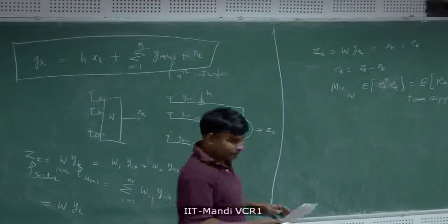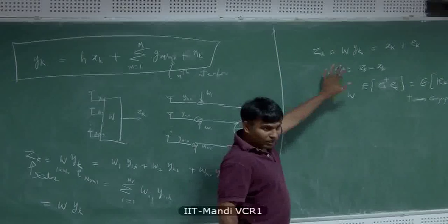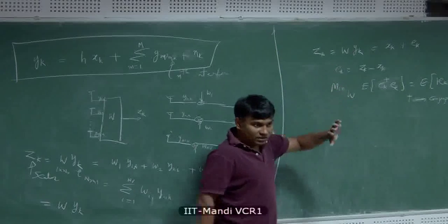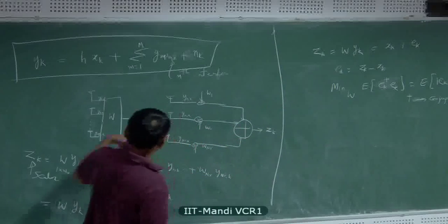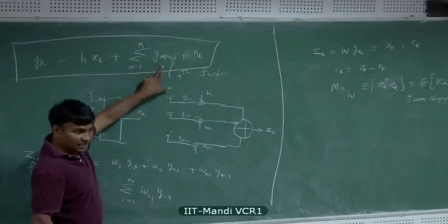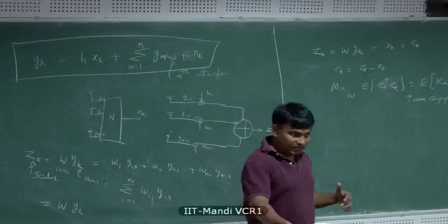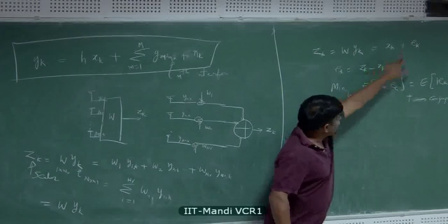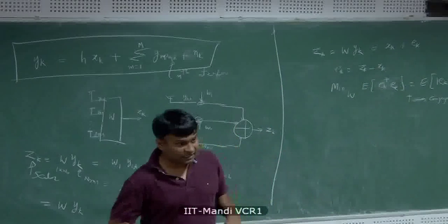Okay? So how the bit rate has increased? This receiver doesn't talk about all those things. That we will show. If this receiver is able to separate all the signals and deliver a post-processing SINR at the output of the receiver, that is 1 divided by the mean square error, is high enough, then we will figure out whether the bit rate has increased or not.